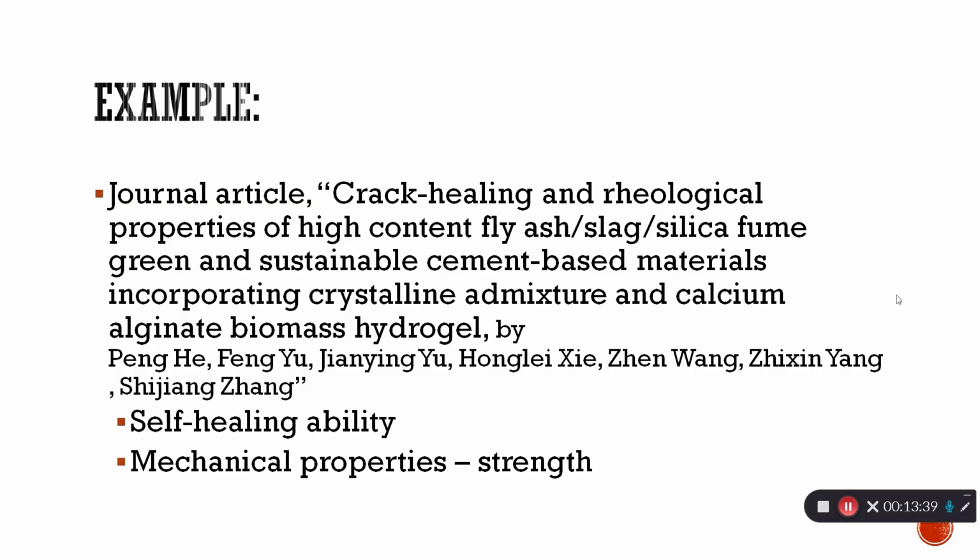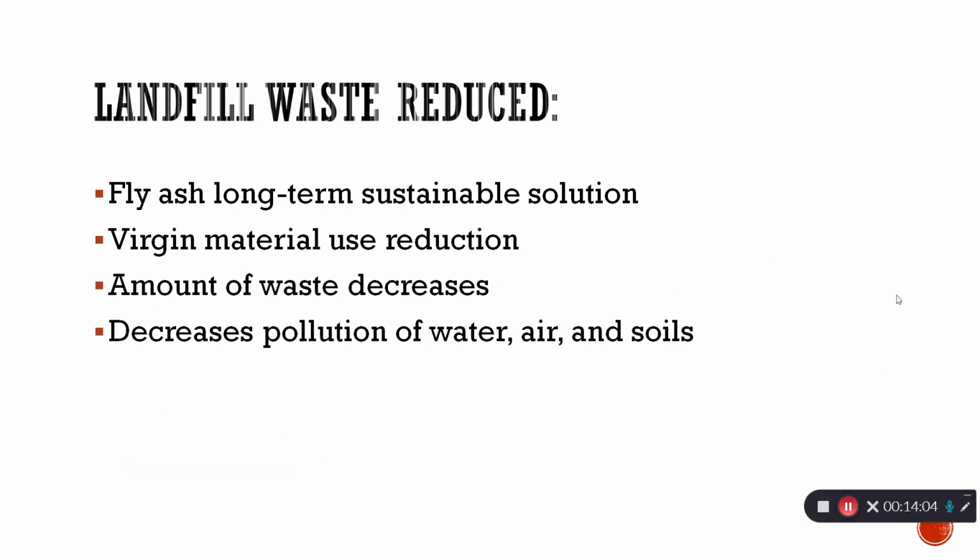This had to do with the shape of the fly ash. It was a large spherical particle and had low reactivity. When it was undergoing the shear process, fly ash was playing a bearing role to reduce friction between particles. The mechanical strength of mortar for the mixture was increased, and the addition of SCMs had the ability to improve the permeability of mortar. Fly ash was observed to have the ability to enhance the self-healing ability of cement mortar. So landfill waste was also reduced through all the review of this.